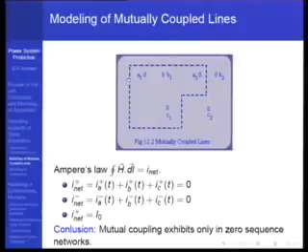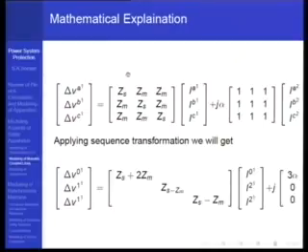Is this point clear? In load flow we don't worry about this, but in short circuit analysis we need to know how close the towers are. If two circuits are on the same tower, then we need to worry about the mutual coupling in the zero sequence, but not in the others. For positive and negative sequence, the circuits can be considered decoupled. Only the zero sequence voltages will come.